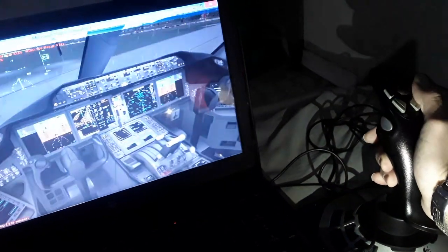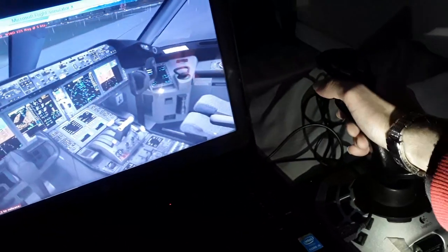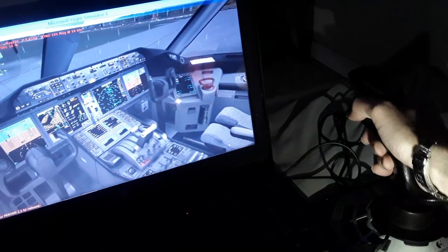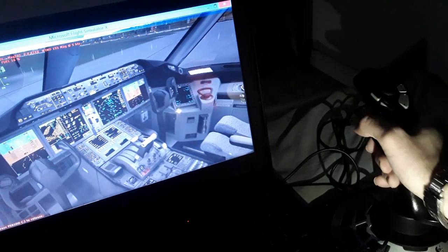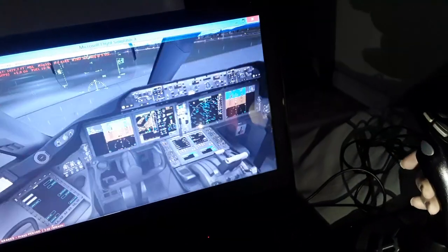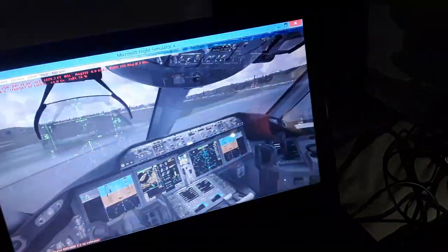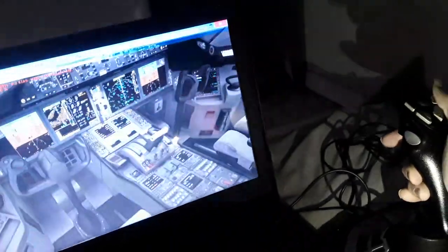All flight controls. Also, you can see the side stick deflection is proportional to the yoke. It's a fly-by-wire aircraft, so when you move the flight controls, you give a signal to the flight control computers. So you have normal, alternate. You can have the flight control computers here. Normal, alternate, and direct mode, like in the Airbus.